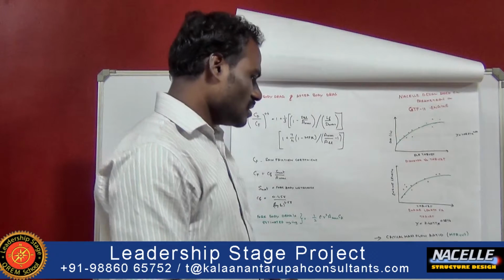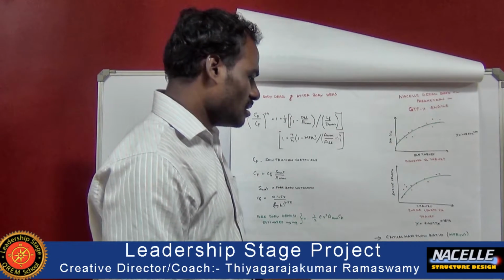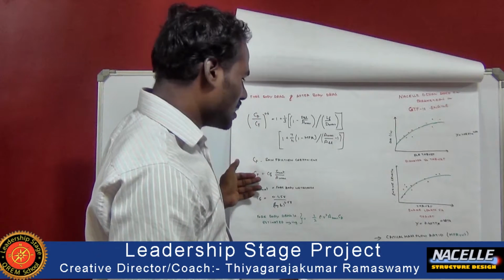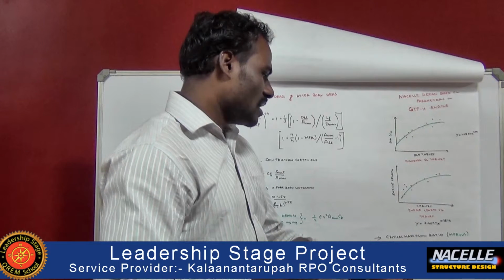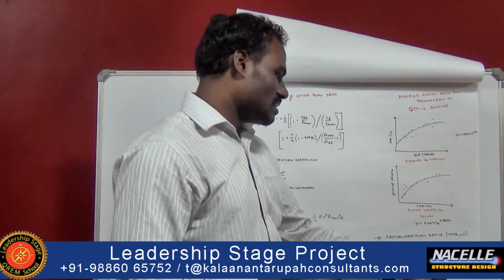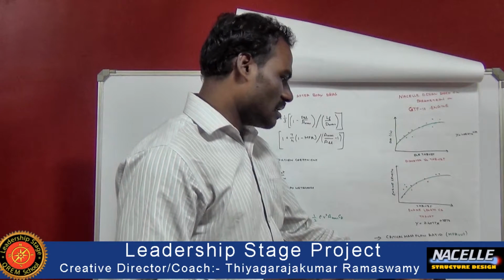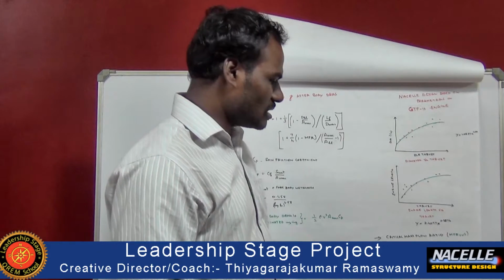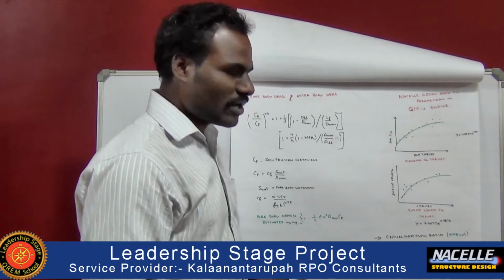0.03876. Then we are going to find out the critical flow ratio, which we have discussed earlier. With respect to the marginal mass flow ratio, if the marginal mass flow ratio increases with respect to Dmax, in the sense the nacelle drag increases with respect to the mass flow rate, the critical mass flow ratio decreases. Usually the critical mass flow ratio will be 0.58.